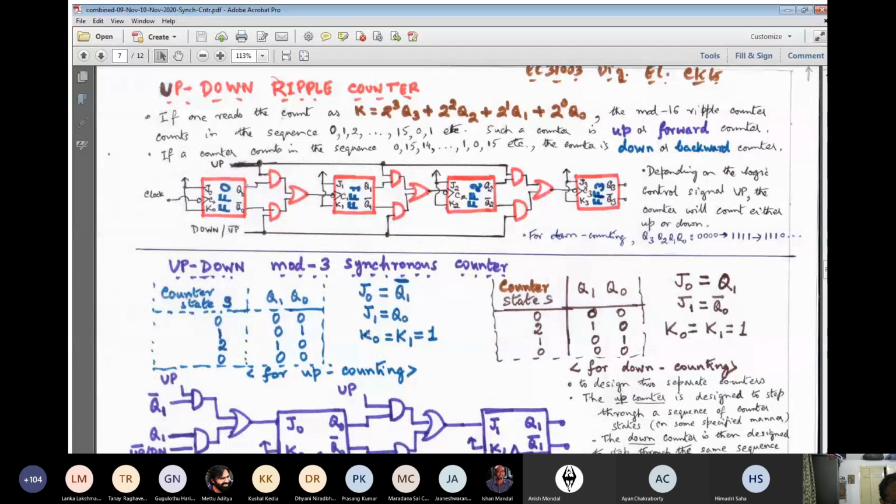So remember that for up counting you require three states. The same three states will be recurring, but in the reverse direction. Let me tell you a word of caution. If you are taking 00, 01, 10, do not by mistake take 11 in the reverse counting. 11 should not come there. Are you getting it? If you take 00, 01 and 10 in the forward direction, you should have the same states only. Do not include one by mistake in the reverse direction. These same three states will be there. Okay, dear friends, do you get it?